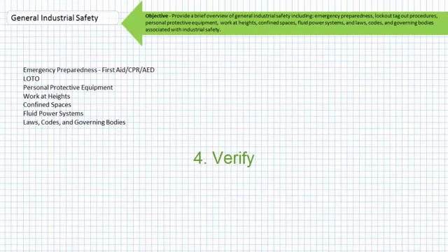Use your voltmeter to perform voltage checks. Read pressure gauges. Look at the thermometer. Check to make sure any lifted weights are blocked out or lowered. Don't just assume things are safe before you begin work. Step 5. Now that you've verified the lockout and tagout procedure was successful, you can perform the service. If you're doing a shaft alignment or oil change, you can do so and don't dilly-dally.